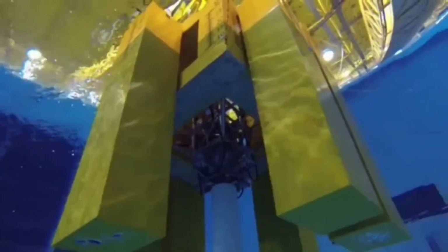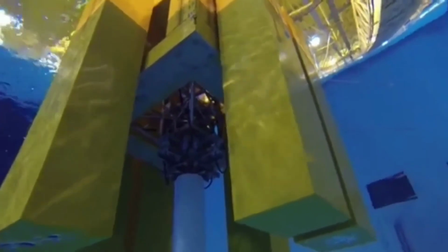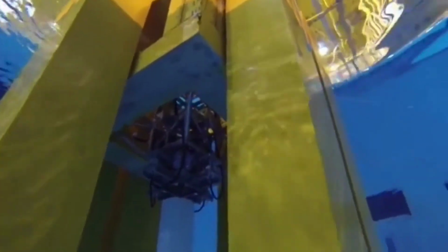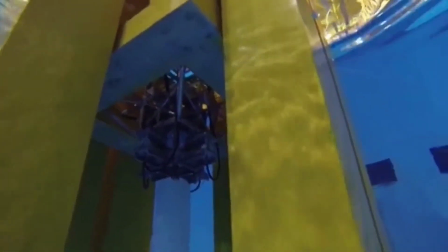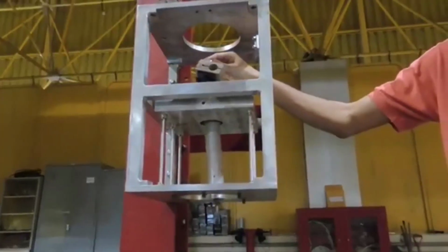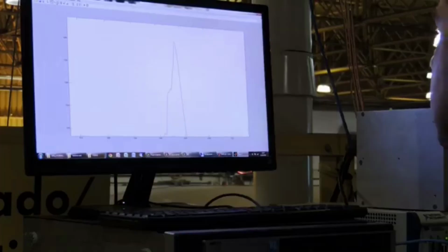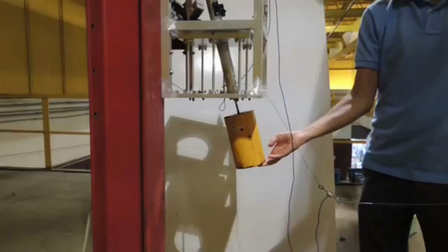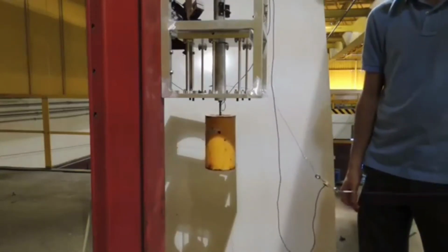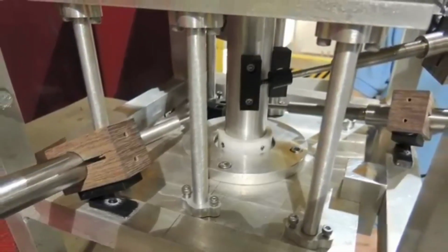In operation, the CWP is coupled to the platform by a huge gimbal, which acts like a universal joint to accommodate the motions and lessen bending strains on the pipe. The model gimbal was carefully instrumented to record forces and angles. 2 different gimbals were tested, a free gimbal and a restrained gimbal.